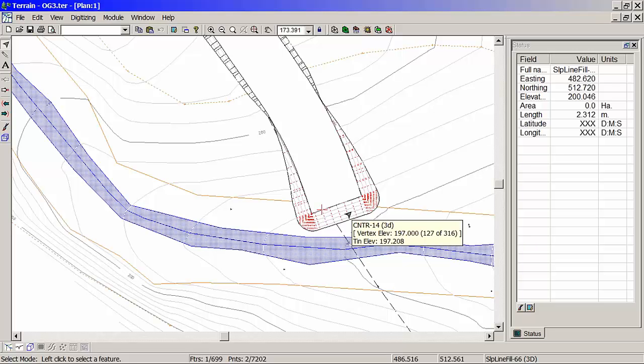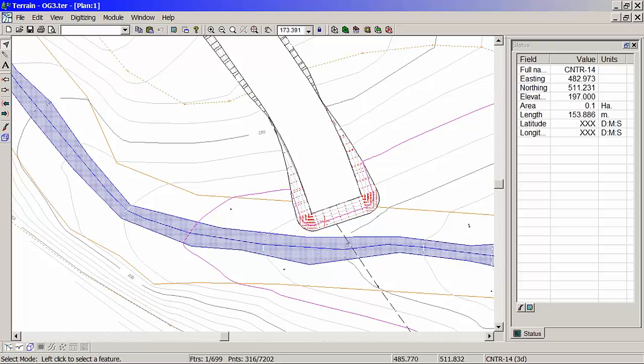Okay, just a little recap of what I've done. Again, brought in a terrain from a design, used the road edges to create a slope down, graded it down to the surface at a 2-to-1 slope, and then merged that into my existing terrain.